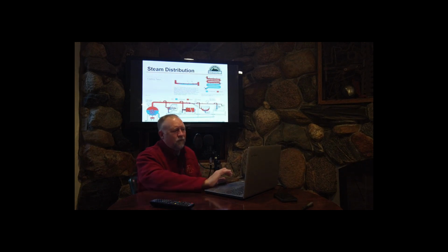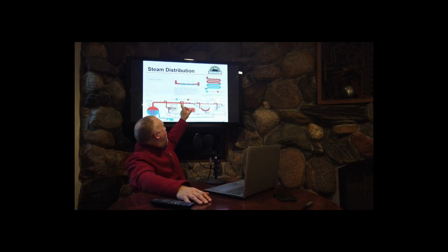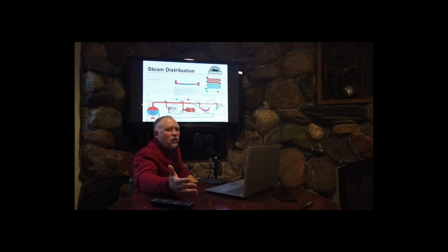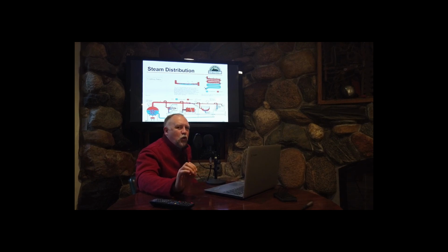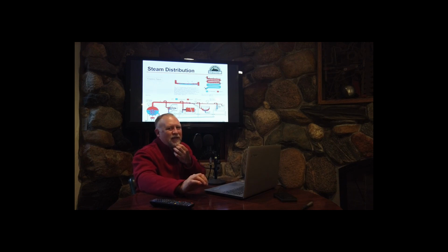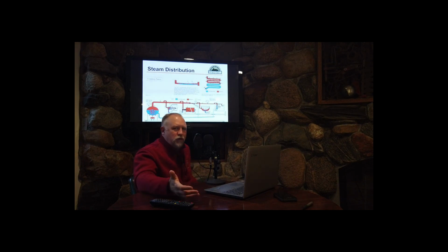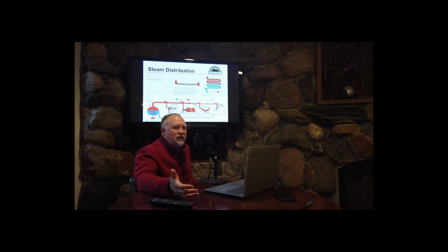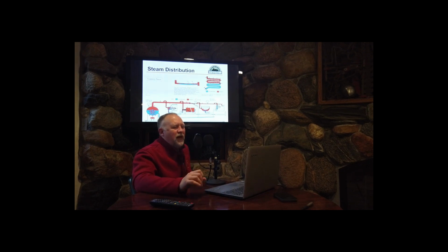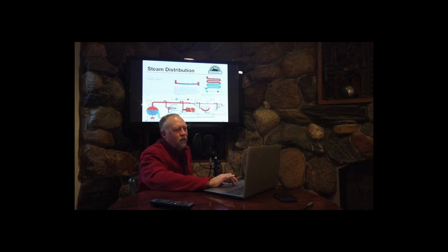Let's go to New York City. Let's say that this is 100 psi steam, like Iowa State or New York City. That means these pressure spikes could easily be 1200 psi. Let's also say in New York City, maybe some of these pipes are 50, 60, 70 years old or older. It isn't unreasonable to think that a pressure spike could cause a catastrophic failure of that steam system and cause it to rupture. And I think that's what happened.